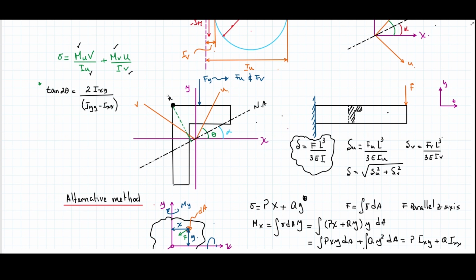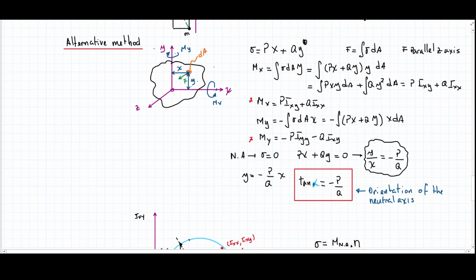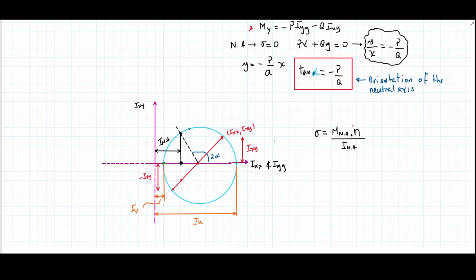So you get to know how much is the stresses at this point n, or n could be, or m inclusive, depending on where you want to have it. Those are the farthest away points from the neutral axis. There you go. Then either on m or n, you can substitute those ones here, and you will get the value of the stresses that you're looking for, or m. I would say this is a pretty nice way of doing this stuff.